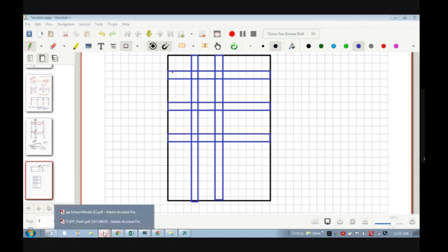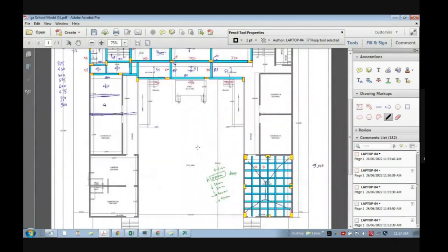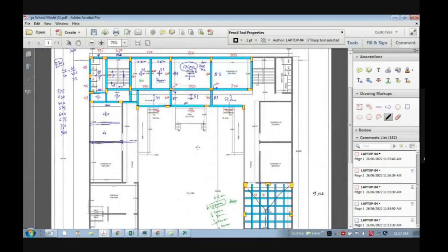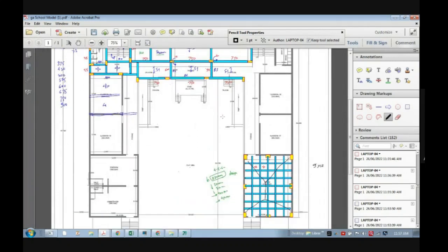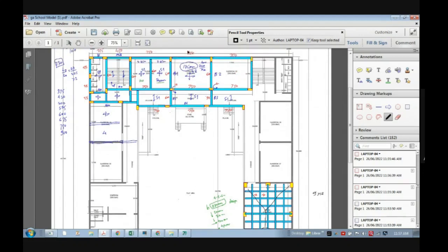And this way we can do, we can say, overall planning of the structure. Once you put the columns, beams, slabs, everything you do, and then once you do that, then you can go to the model of ETABS and do the modeling of ETABS, then design it, check it. If the design is not satisfied, if the depths are not sufficient, increase the depth, increase the steel, whatever you want, and then go.